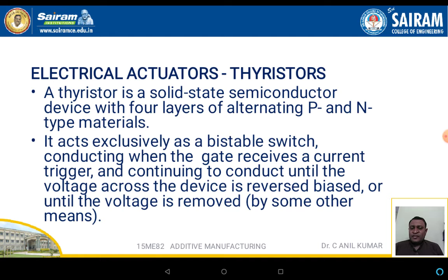Electrical actuator. In this, the thyristor is also one of the actuators. A thyristor is a solid state semiconductor device with four layers of alternating P and N type materials. It acts exclusively as a bistable switch, conducting when the gate receives a current trigger, and continues to conduct until the voltage across the device is reverse biased or until the voltage is removed.